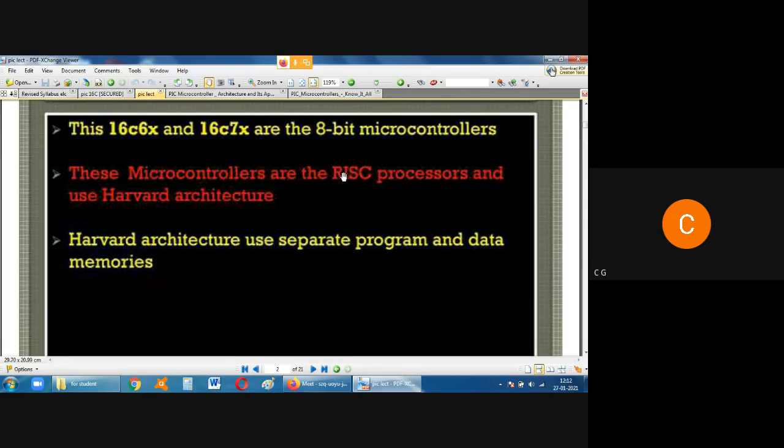CMOS, why CMOS is preferred? You can accommodate lots of transistors. So the transistor density increases with the use of CMOS. Okay, BJT is the basic one. So transistor density is one of the parameters. Secondly, the power consumption in the case of CMOS is very less, right?